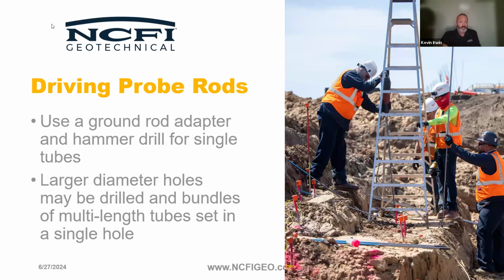Driving the probe rods. Typically we use a ground rod adapter with a hammer drill. The bigger hammer drills, like a Hilti TE60 or TE70, have a ground rod adapter you can put on the end.